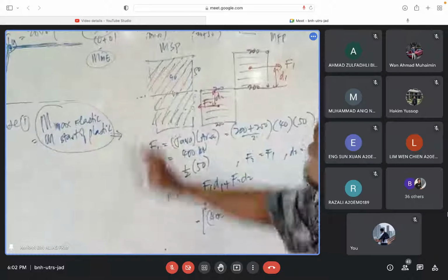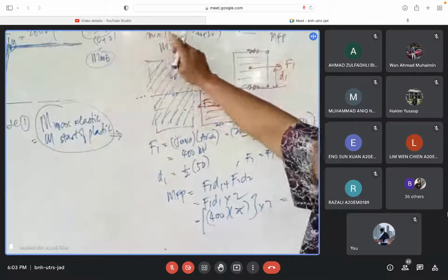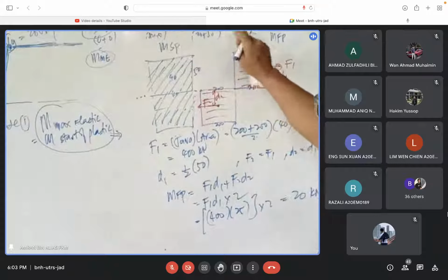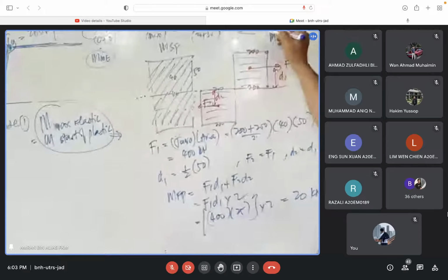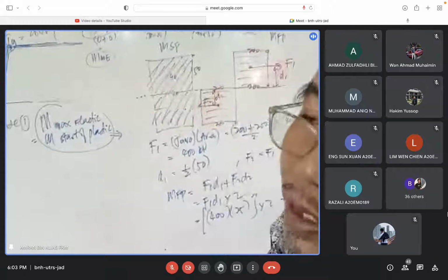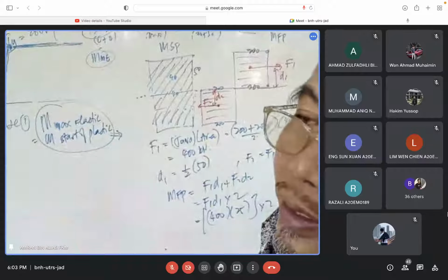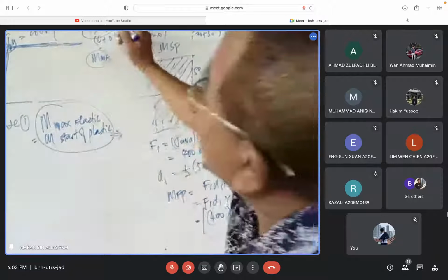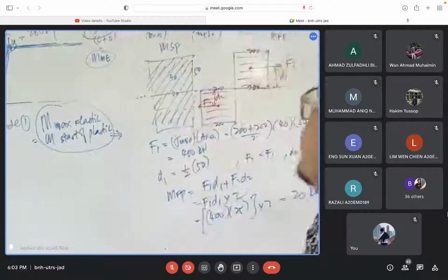So start from 13.3, 13.4, you can do the work. Start 14, 14.5, 15, 15.2, until 17, 16, 17, 18, 19, 19.1, 19.9, you still can work. But cannot be higher than 20. Higher than 20, the material will collapse during the process of bending it. So now this is a point. The load must be higher than that, must be lower than this.